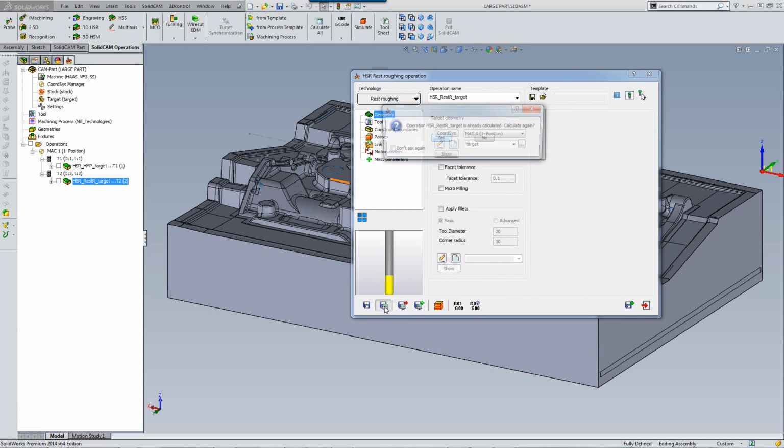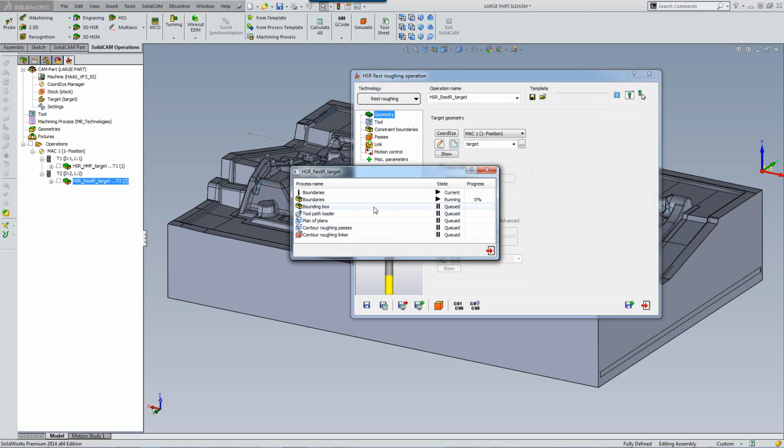This time you'll note when I start the calculation, it's again building the STL for the part itself, but you can see now how quickly everything is done inside this one box itself, much quicker than it was in the previous calculation of the part. Now, if we were to compare this to a large part, where previously it used to take 1 hour to calculate in many cases, it will now take about 25 minutes instead. A large saving on time as far as calculation of the parts.